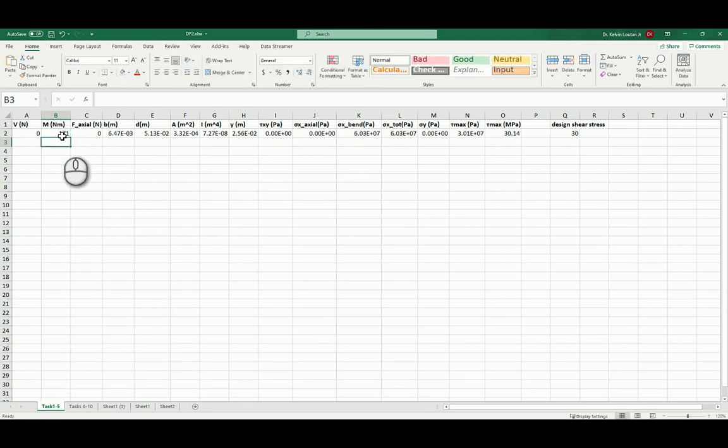Right, so we could tune it down, but there's no need to really do this fine tuning. Well, perfect. Right, so 170.2 Newton meter, we're saying therefore, is the maximum pure bending moment in a static sense that this particular cross section could handle, given a factor of safety of 1. Alright, so this is how the design process works when we have an open-ended problem, meaning that we have the design stress, and in this case, we're solving for M.